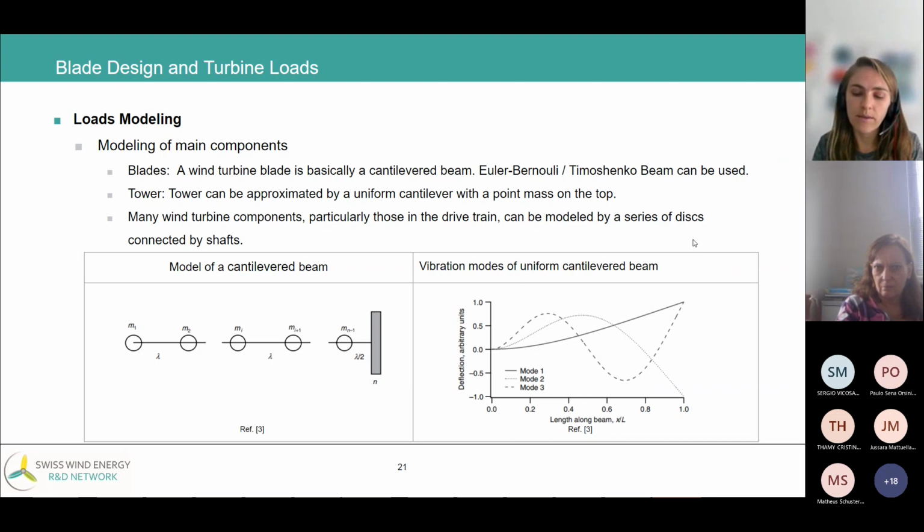You also need to have the transformation of the coordinates. On the blade, you have a coordinate system that's rotating. Once you pass from the blade to the shaft, you do a transformation of these coordinates in order to be in the coordinate system for the shaft, and then have the inertia calculated for this shaft.